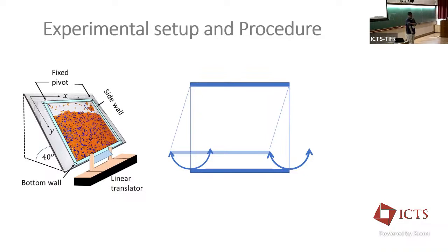You're right that this arm and this arm are not the same. This arm is a pushing arm. This arm is only a confining arm. They're not doing anything because I can't, this is granular stuff. I can't pull on it, right? So all that this arm does is just provides you some kind of confinement to it, while this arm is pushing. So this arm gets pushed up. When this arm starts to move in, then this arm becomes a confiner and this arm becomes a pusher.